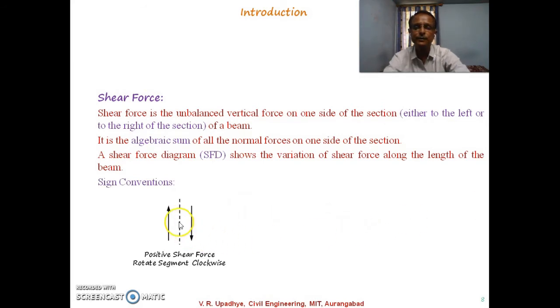Generally, the sign convention used is something like this. If we are considering a section in between at a particular position on a beam, then for the left part, upward forces will be considered positive. And if we are considering the right part of the section for the analysis, the downward forces will be considered as positive shear force. So it rotates clockwise. It rotates the segment